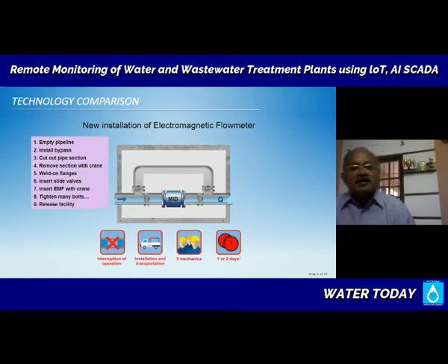First of all, ask what is the technology available for this? What are the challenges that I will have if I have to provide measurement in a wastewater system? Then how to overcome that? What is the equipment? Vendors will come and tell us, oh, here is what I make, you use it. If you think there will be partial pipe flow, then reduce the pipe diameter.